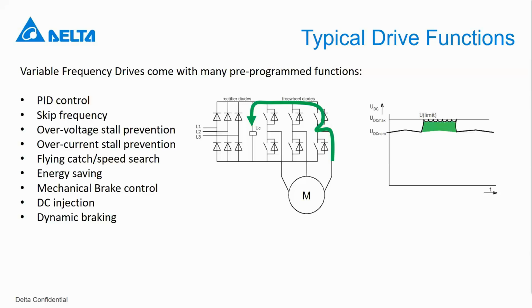This means that the DC voltage will increase, and the drive has a protection function to just automatically trip to disconnect from the motor when the DC bus voltage reaches 820 volts. But if the drive disconnects from the motor, then the motor will no longer stop within the programmed amount of time. It will just coast to stop. So it will stop based on its own inertia.